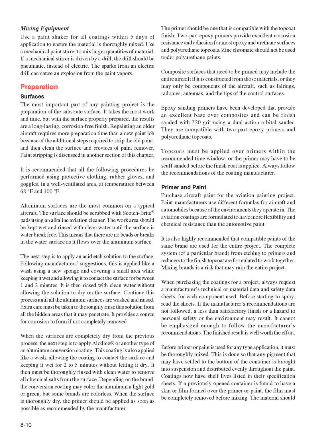When purchasing the coatings for a project, always request a manufacturer's technical or material data and safety data sheets for each component used. Before starting to spray, read the sheets. If the manufacturer's recommendations are not followed, a less than satisfactory finish or a hazard to personal safety or the environment may result. It cannot be emphasized enough to follow the manufacturer's recommendations. The finished result is well worth the effort.